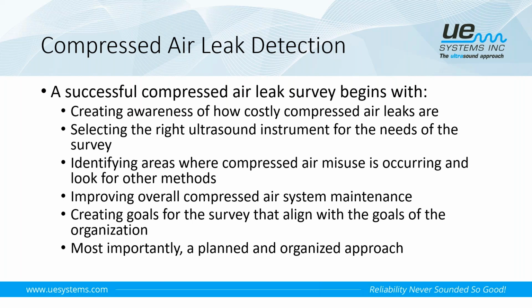Again, what kind of data do we want to get out of it? Who's the primary user going to be? And maybe we want to start out with compressed air leak detection now, but in the future, we want to grow the ultrasound program. So selecting an instrument that would be suitable for any kind of future use would also be something to take into consideration.